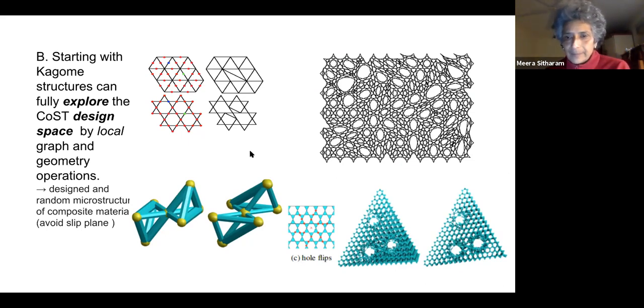The second design operation that I'm writing about here is the addition of irregularities. We're selling this as having a common representation that can represent naturally occurring microstructure, composite microstructure, printed microstructure, irregular microstructure, everything, with different physical properties. So we need a standard way to generate irregularities and to analyze the effect of those random microstructures, and, for example, print them. We proved some theorems to show that you can actually explore the entire design space using flips.